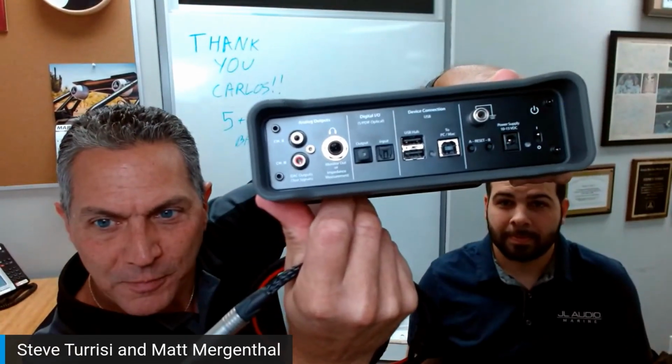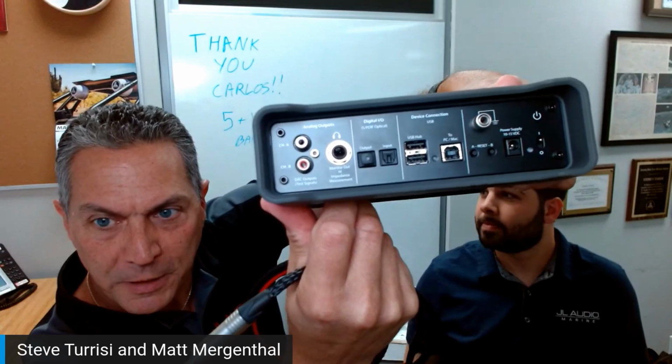So the impedance one is going to use this 1/4-inch jack, which you'll plug into the... On one side of Max, you'll have this, there we go, that guy there. And it's a monitor output or impedance measurement. So we'll take that and we'll jack it in there. On the other end, we have the business end, is what I call it, where we can connect our probes. And we have other probes here that are a little bit easier to work with. And we're going to measure the impedance of this speaker. So Matt, you got all that stuff already set up instead of my props?